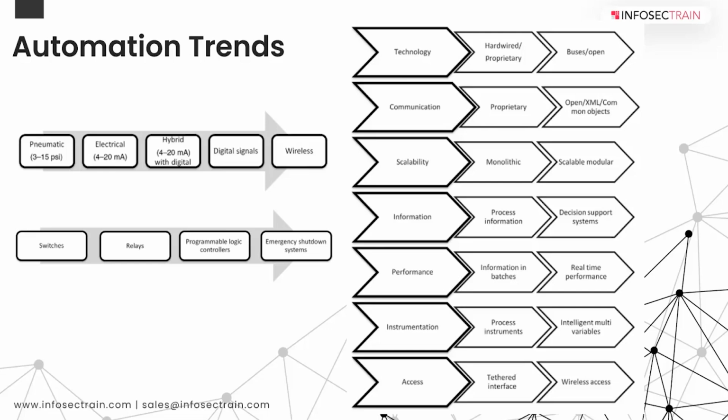As I was saying, the instruments are becoming more smart, and earlier used to be dumb, right? And now there are inbuilt diagnostic features which can prognose what the issues are, and it helps the operations and the maintenance. Instead of having them replaced during shutdown, we can proactively order the components or get a replacement and so on.